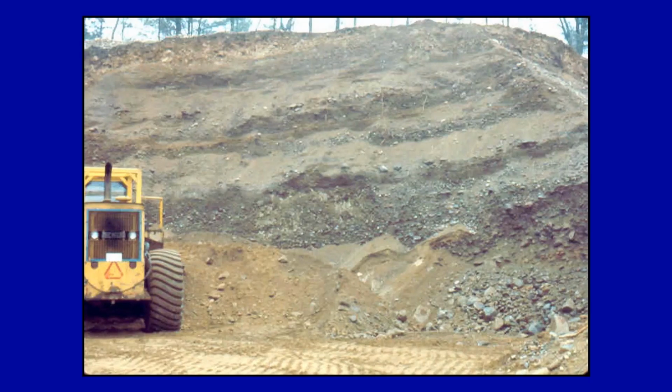Here we have an outwash plain. And as you can see, during the summer, there is much more melting going on. And in this particular case, it probably was a warm summer with much deposition going on. A moderate winter, a very cold summer, followed by an even colder winter. So this is the type of material that in sand and gravel deposits will in fact be potential for a high yielding well.